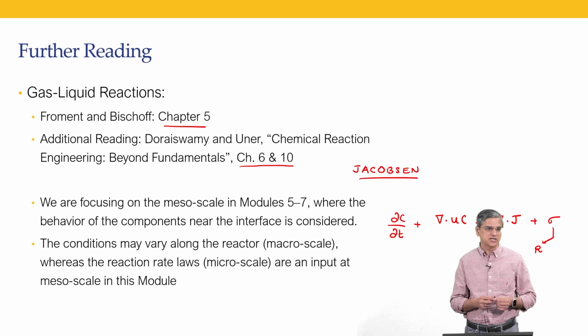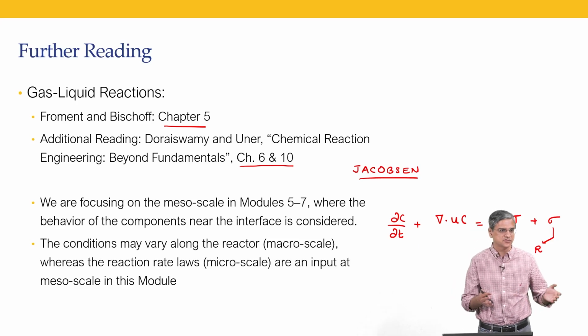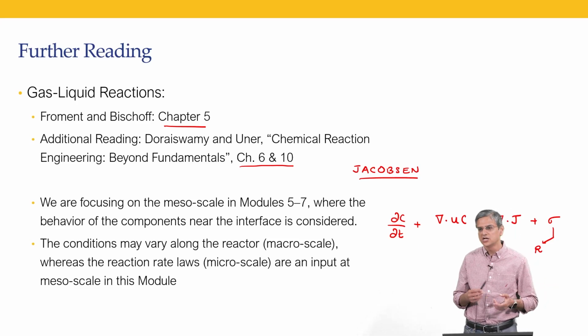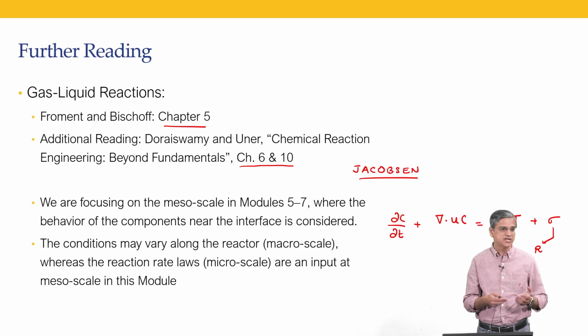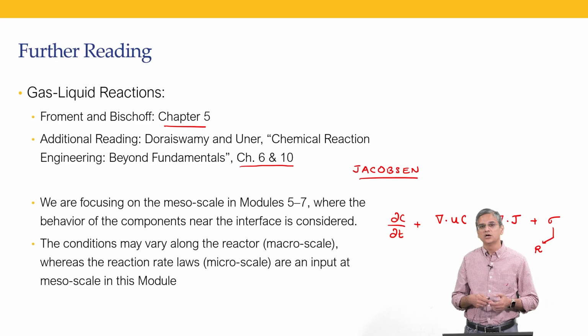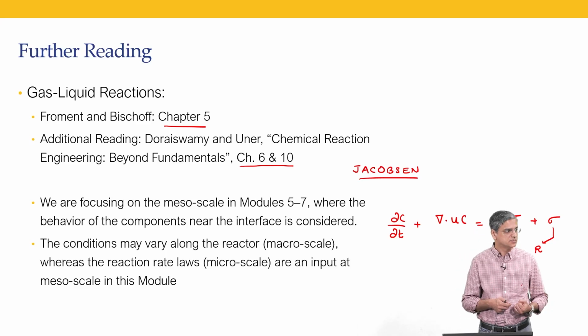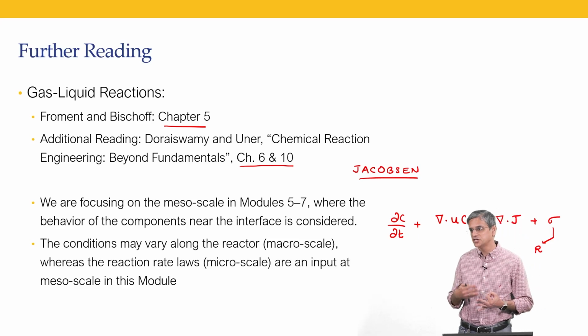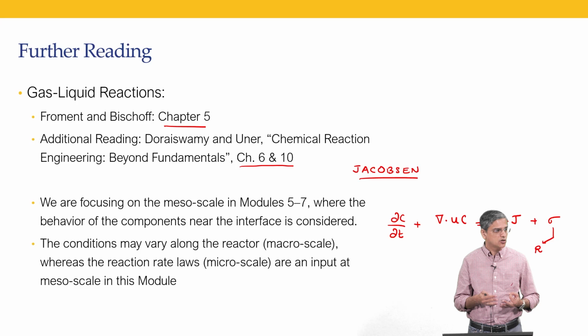But source term basically means anything that happens within a control volume because of various factors. So, for example, when it comes to heat transfer, a common source term would be the energy balance. There would be kinetic and potential energy, right. So, potential energy would be an energy source term in sigma. If there is radiation heat transfer, it will come in sigma. If there is heat of generation or release because of reaction, that will also be captured in sigma.